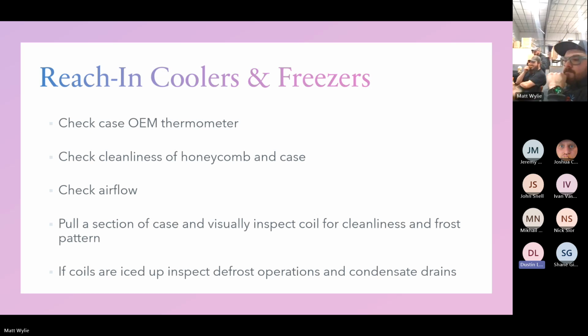So if you do have a termination sensor, it's got to be on the coldest part of the coil or the coldest U-bend, because if it's on the furthest away from the expansion valve, or it's on the warmest part of the coil, or it's near a defrost heater, it's going to get to temperature and terminate before all the other parts of the evaporator have defrosted.